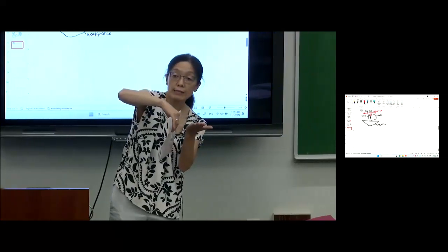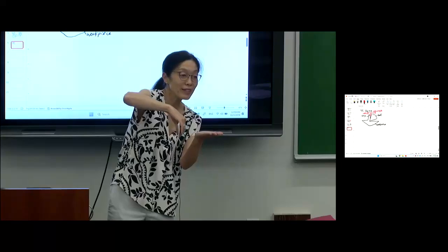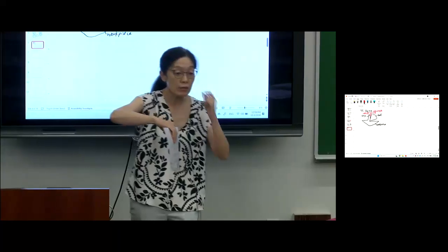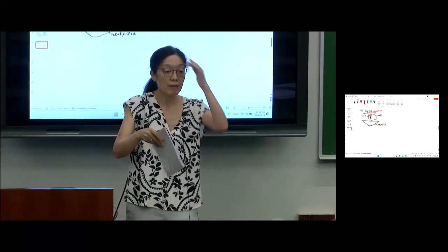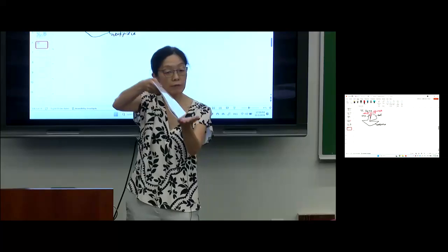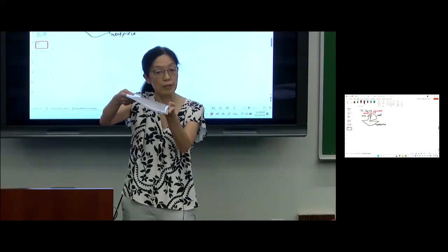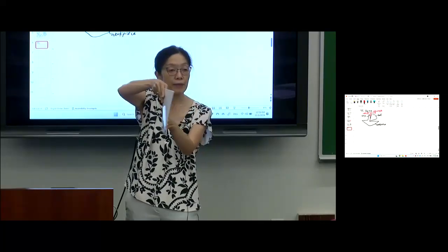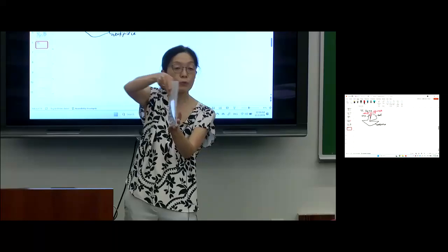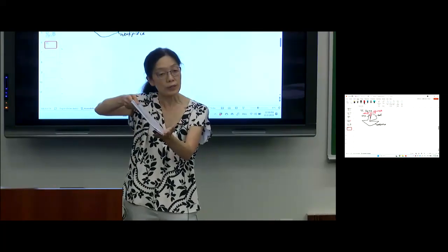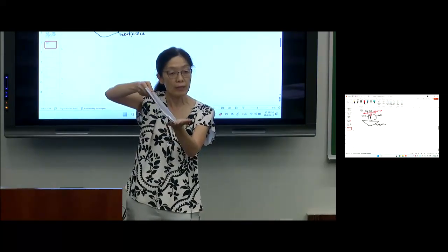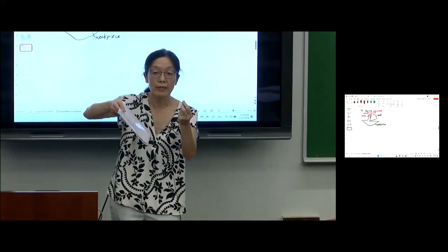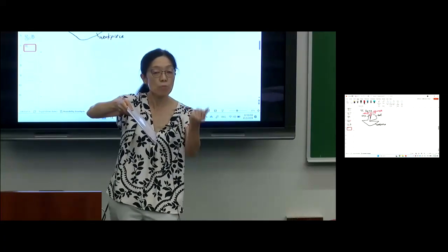But why do we have this case? There's a reason, right? Everything has a reason. Otherwise, it disappears, right? So then why? Because if it goes like that, I said it's going to chip. So then if you go like this, maybe much more rigid, tougher, and then go even tougher. So if you use metal or tungsten carbide, I don't know what kind of tool you use, usually go this way. But if you use a ceramics tool, diamond tool, then that's hard, right? But it's fragile. It's going to chip quickly.